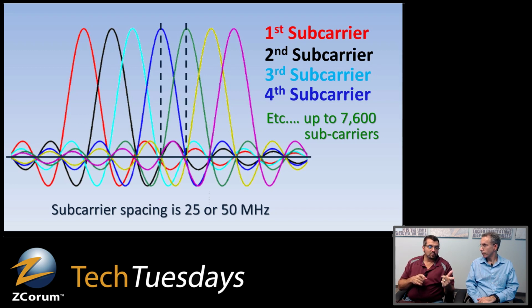With OFDM, when it actually sends it, it sends pieces of the code word across subcarriers at different frequencies, as well as time. So if you've got some interference somewhere, it's not completely wiped out because it's not all in one place, right? The actual code word comes across time and frequency. So they did a lot of things like that.